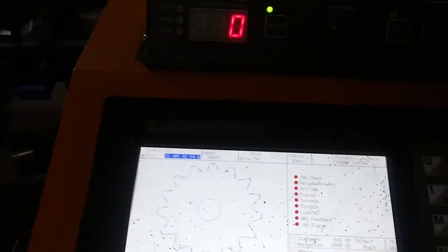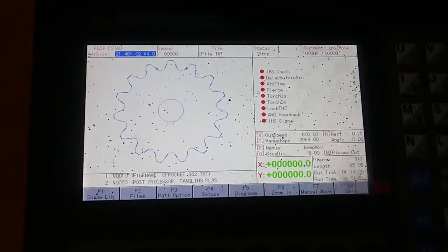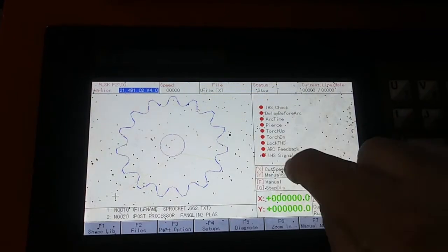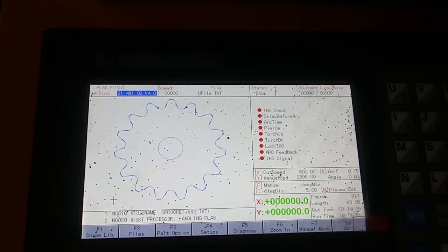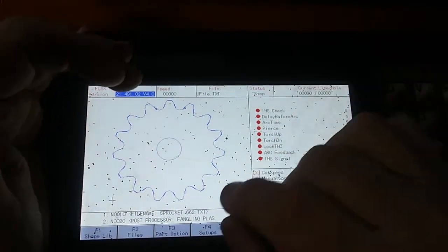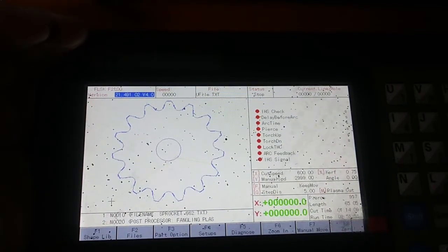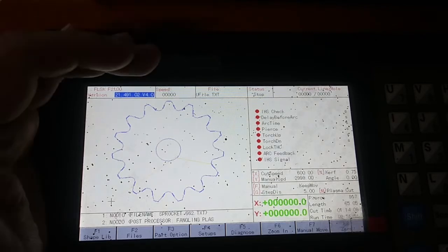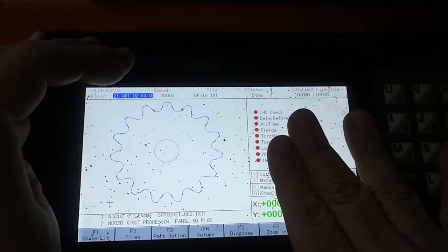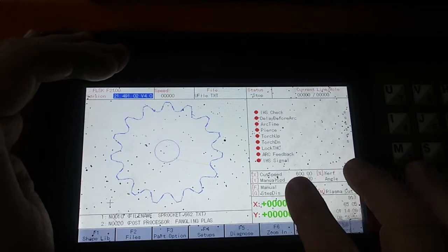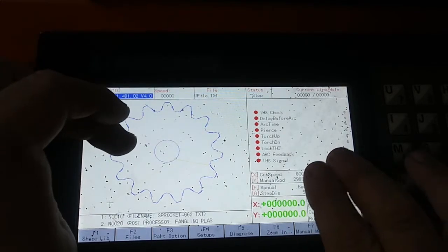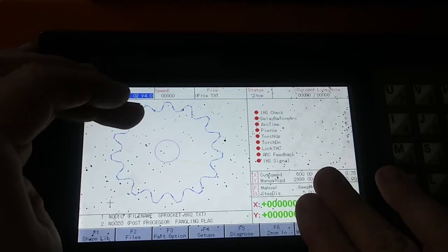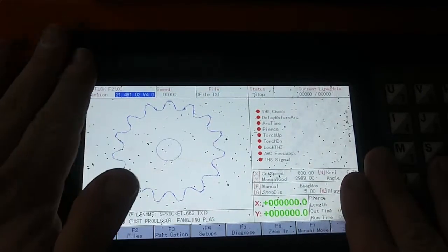In this video, I'm going to be doing some troubleshooting, and show you how to get your cut feeds or cut speeds correct. Let's say you run software or G code from something like SheetCam or Fusion, and you transfer the file onto this controller, and the cut speed doesn't transfer from the G code to the actual controller, or the speeds are different. What ends up happening is that these are not synced together.